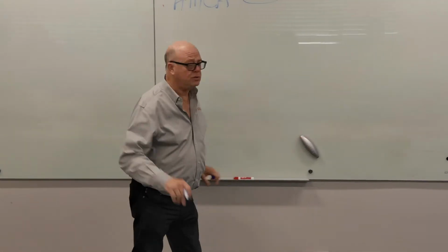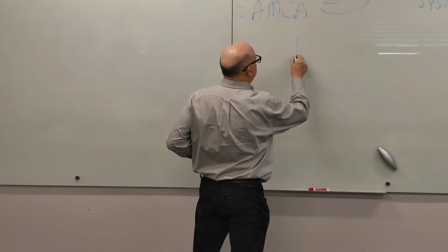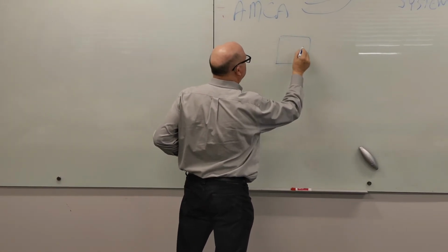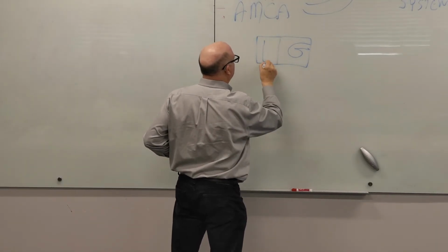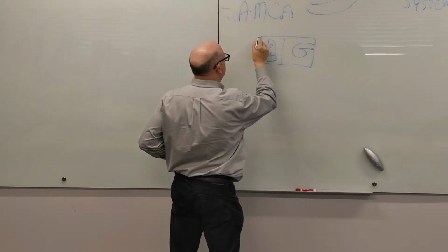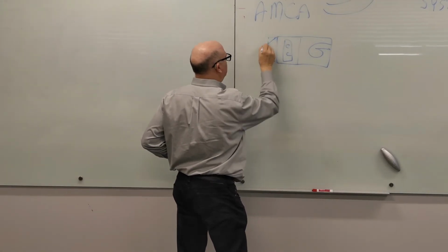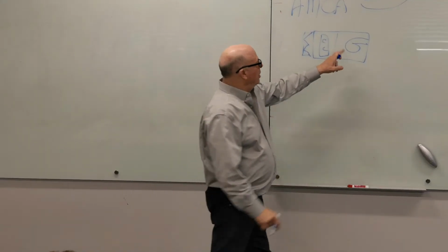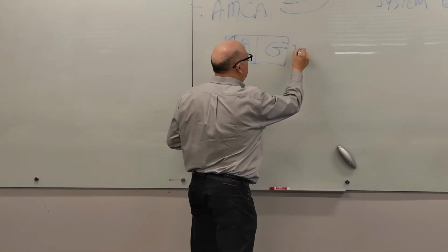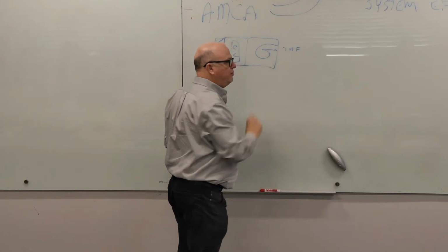air handling units. So if I've got a horizontal draw-through fan, which means that it's horizontal, and I've got a cooling coil, and some kind of little filter housing, and whatever else. This is a top horizontal front discharge.